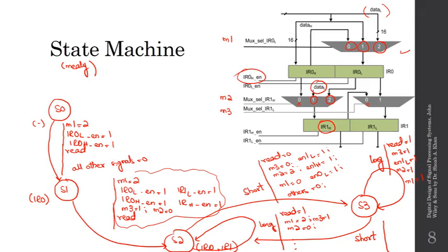After processing this whole operation, we'll be left off with IR0 as empty, which S3 is already stating to us, because at S2 no register is empty, but at S3 only IR0H was empty. That was because a short instruction was processed. So this is one of the formulations of the FSM, given that we make use of a Mealy machine.